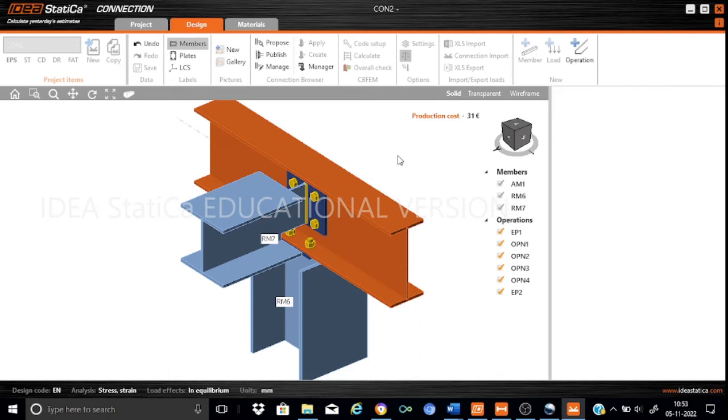And one thing here I want to mention, this Idea Statica Member will never design any connection. It will not check any of these connections. Another important point is that Idea Statica neither asks you what the boundary conditions are, whether it's a pin or, for the continuous beam, a fixed support, and it calculates the support conditions itself based on the rigidity of the connection.